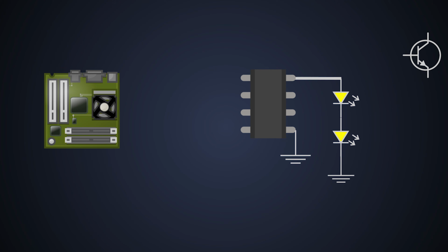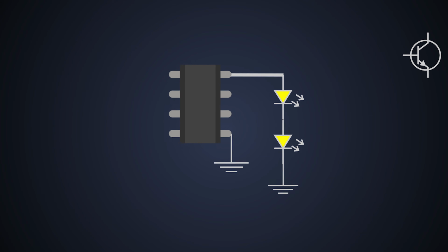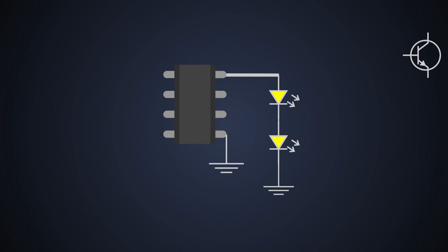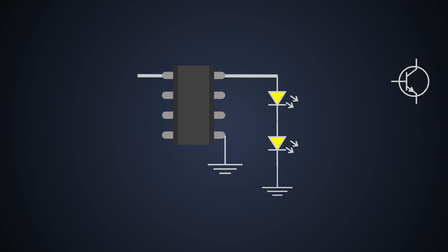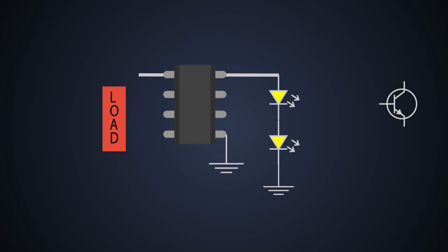Let's take an example where we have some load like a CCR with LEDs or an embedded system. Every IC or power supply has some input voltage range in which it works without damaging. Let's take an example of a CCR. I just love lighting loads. Those are just very easy to explain. We can use both NPN and PNP transistors for overvoltage protection. In this video, we'll see the NPN transistor which can be used for overvoltage protection.